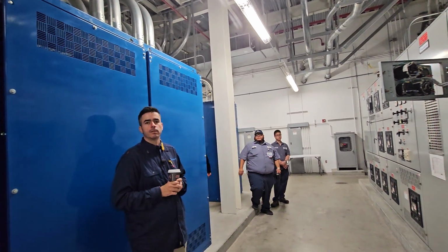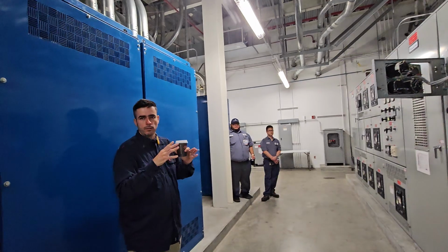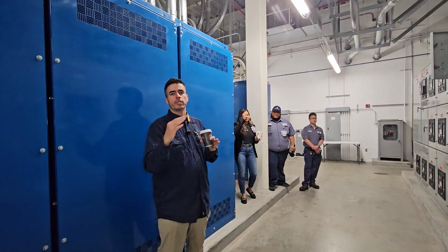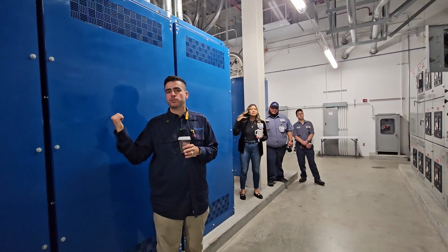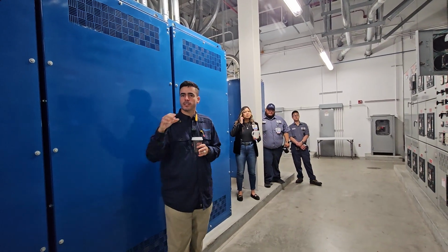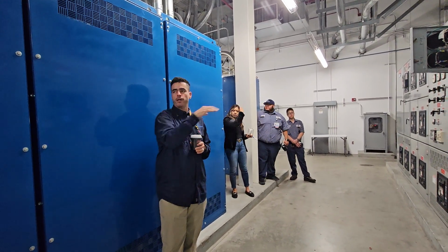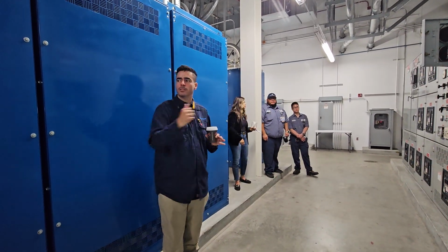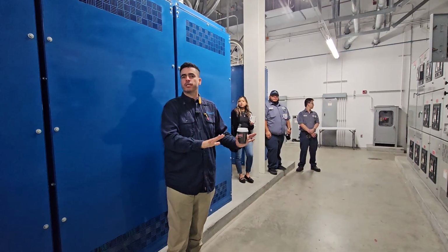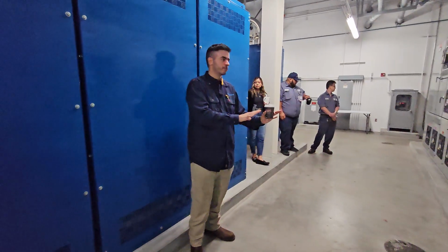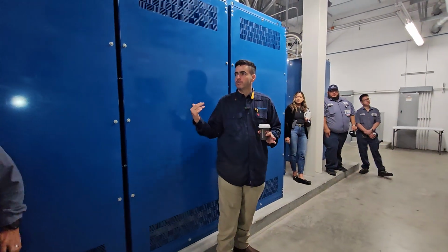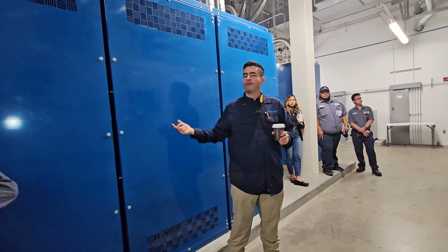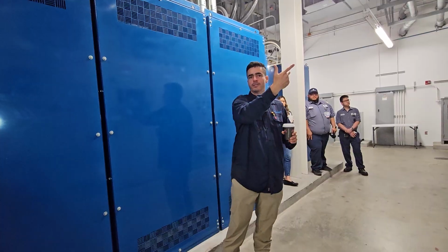Yeah. So the ATS has its own system, its own controller that is going to determine when to transfer back and forth. All it needs is to see power. Once the ATS is sensing normal and emergency, like right now it's sensing normal, so it's not going to do anything. Even if we apply emergency, it's smart enough to stay there because that's the preferred source, right? But if it loses power, what is it going to do? It's going to say, hey, give me power. And all it does is send a signal to start the generators, right?